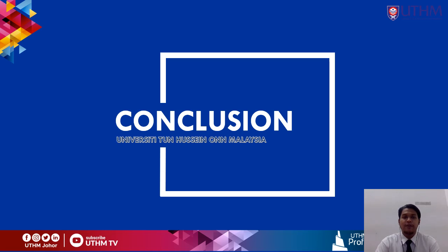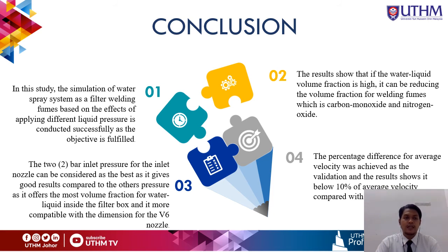Lastly, in chapter 5, I will conclude based on all the results and discussions that I have done. First, in this study, the simulation of water spray system as a filter for welding fume based on the effects of applying different liquid pressure is conducted successfully as the objective is fulfilled. Second, the results show that if the water liquid volume fraction is high, it can reduce the volume fraction for welding fumes, which is carbon monoxide and nitrogen oxide.